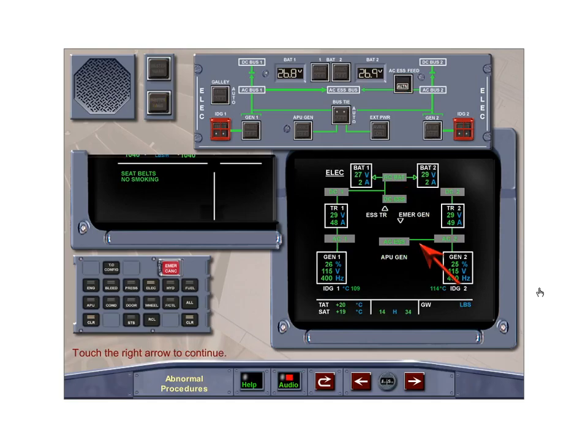If the transfer of power to AC Bus 2 is successful, the equipment powered by the AC Essential bus will return to normal. If the electric push button on the ECAM control panel is selected, the electrical page will be displayed on the lower ECAM. Notice that the AC Essential bus is now supplied by AC Bus 2 through the AC Essential Feed contactor.